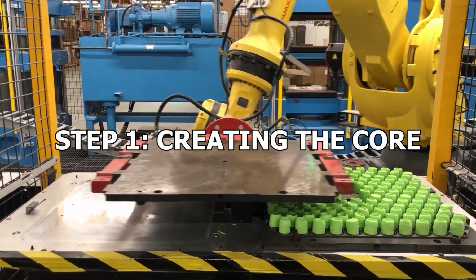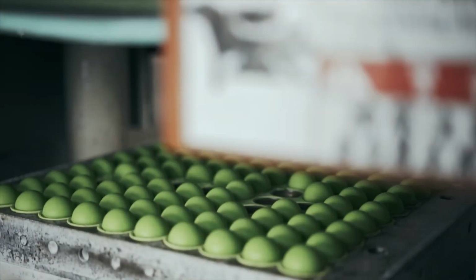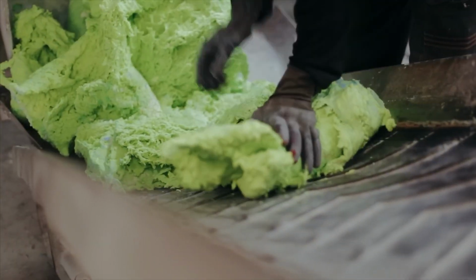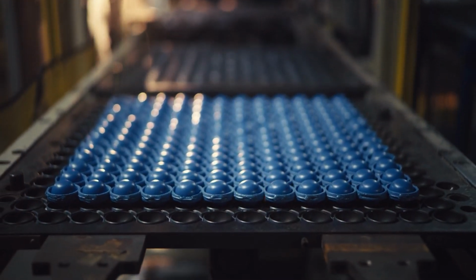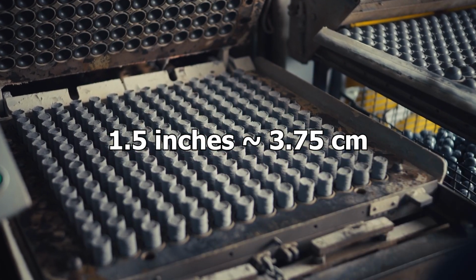Step 1. Creating the core. The core of a two-piece golf ball is formed through a process known as molding. This involves a blend of several chemically reactive ingredients that form a rubber-like compound. The application of heat and pressure results in a molded core, typically about 1.5 inches, 3.75 centimeters in diameter.